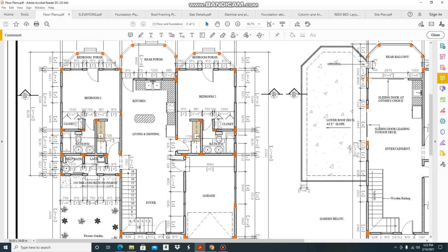And another thing that is of note where the floor plan is concerned is your section symbol. This is, if you can see the cursor going around this symbol here, this represents your section cuts, and the direction in which the triangle is pointing is the direction that you're viewing or seeing when you actually do the section cut. And if you notice, it is labeled section AA.